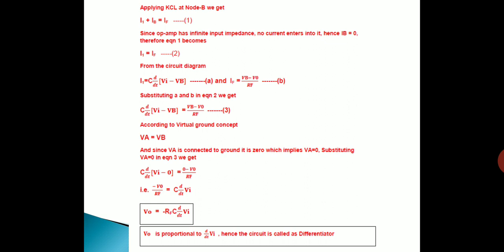If you substitute these two currents in equation 2 and simplify, we get the output equation, and we can show that it is proportional to the derivative of the input. And we have arrived at this output equation by using a very important concept in the op amp called the virtual ground concept.